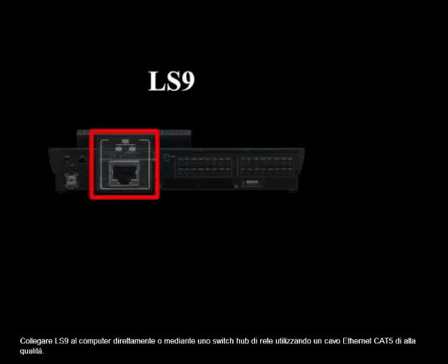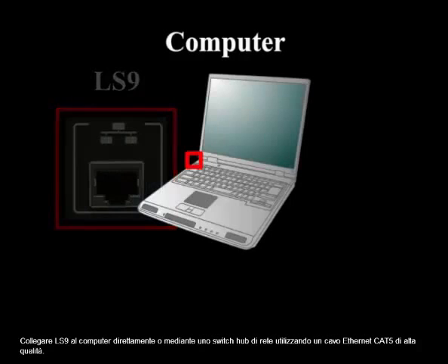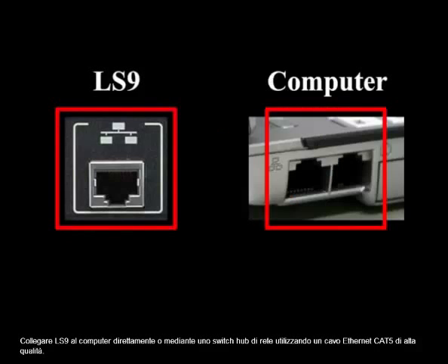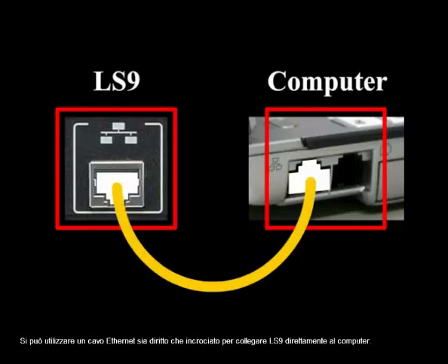Connect the LS9 to your computer either directly or via a network switch using a high-quality Cat5 Ethernet cable. Either a straight or cross Ethernet cable can be used when connecting the LS9 directly to the computer.